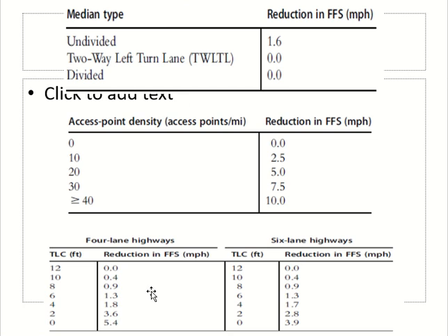So what we will do, on the left hand side, we'll take the value of the lateral clearance to be 6 feet, which is ideal, the base condition, as I showed earlier. So for example, you have undivided highway. The right hand side lateral clearance is 4 feet. It's undivided, so there's nothing on the left hand side. But according to this approach, we'll take the left hand side to be 6.